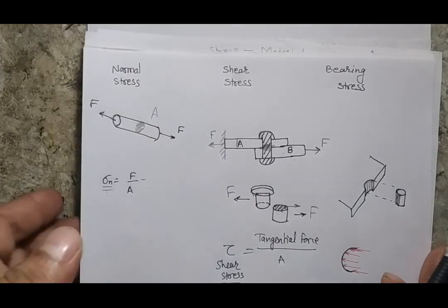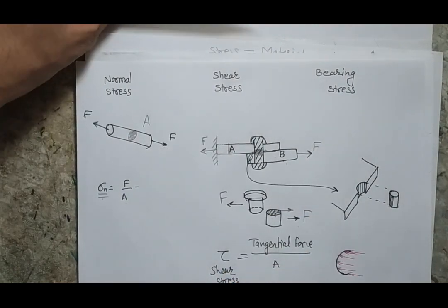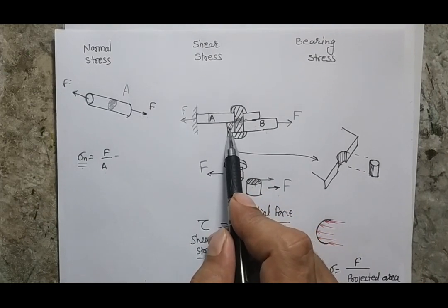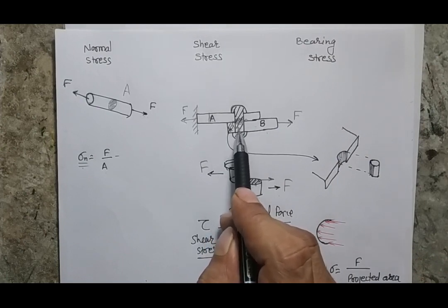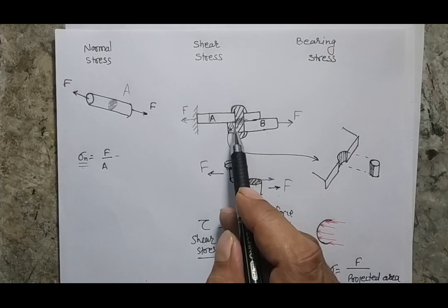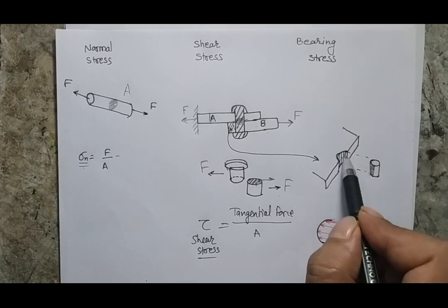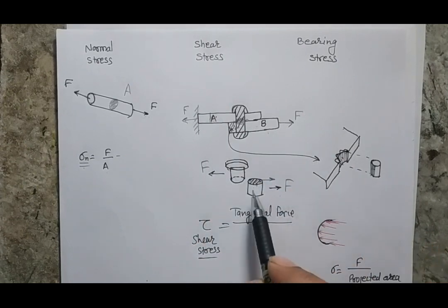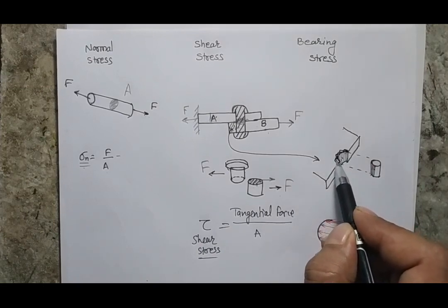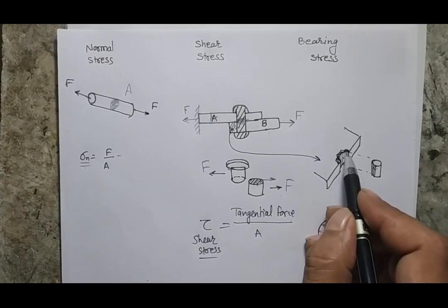If we look carefully, we will observe this small portion diagram here, which has a semicircular hole, and there is a connection or interface between the rivet surface and the surface of the plate. If the material is not so hard, and because there is mutual reaction, the surface gets distorted. Now there is no tearing failure in the plate, and no failure in the rivet. Instead of these two failures, there is a third failure, a deformation in the surface, and because of this mutual reaction, the surface no longer remains semicircular but becomes oval or some different shape.